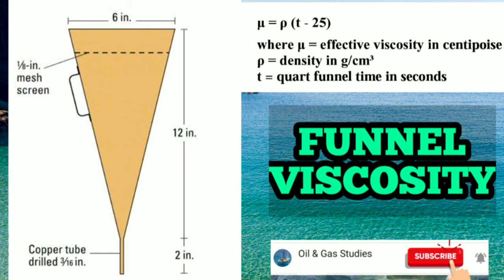In use, the funnel is held vertically with the end of the tube closed by a finger. The liquid to be measured is poured through the mesh to remove any particles which might block the tube. When the fluid level reaches the mesh, the amount inside is equal to the rated volume. To take the measurement, the finger is released as a stop clock is started, and the liquid is allowed to run into a measuring container. The time in seconds is recorded as a measure of the viscosity. This is usually calibrated to read 26 plus or minus 0.5 seconds when testing with fresh water.